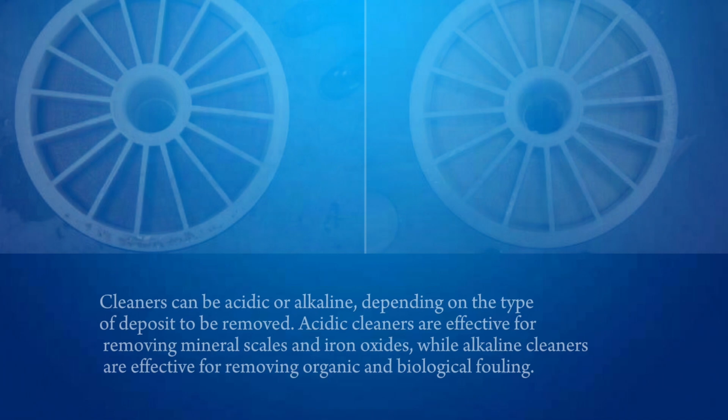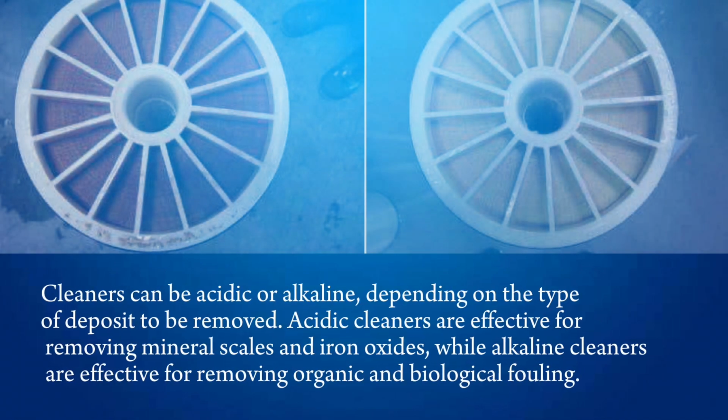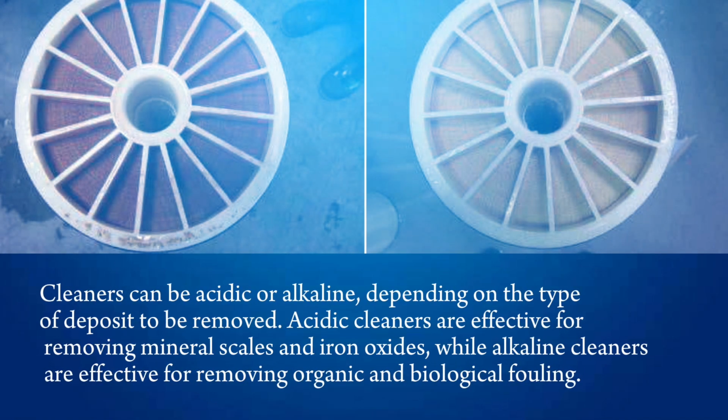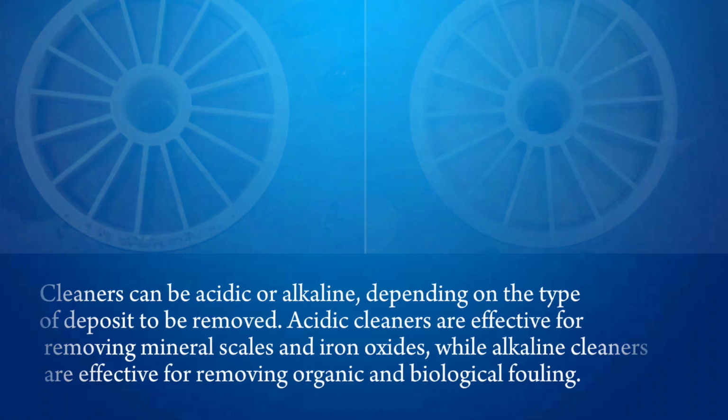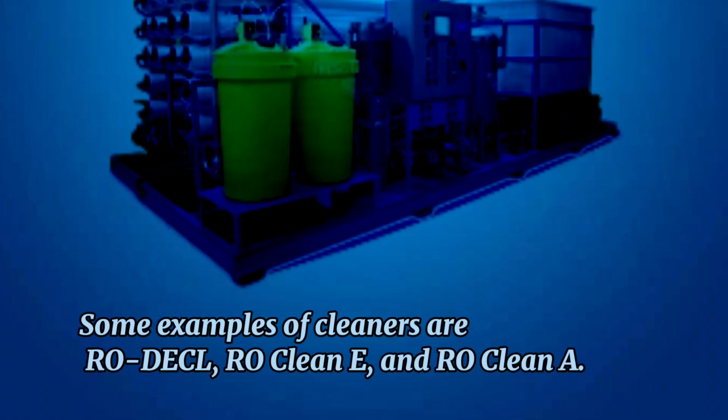Cleaners can be acidic or alkaline, depending on the type of deposit to be removed. Acidic cleaners are effective for removing mineral scales and iron oxides, while alkaline cleaners are effective for removing organic and biological fouling. Some examples of cleaners are RO-Dechl, RO-Clean-E, and RO-Clean-A.